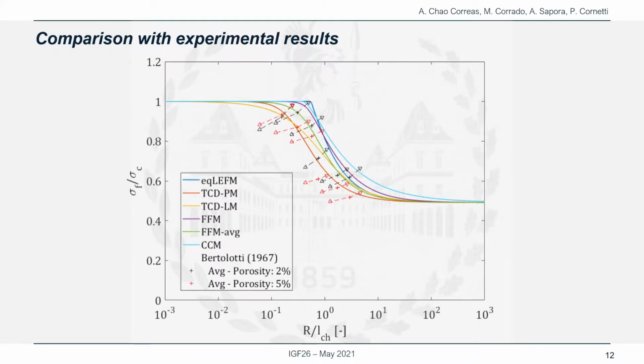Eventually, the experimental results of Bertolotti and Fulrath are a useful tool to check the validity of the method presented and developed here. However, the brittleness of the material used, borosilicate glass, makes it really important to control the experimental procedures. For this experimental campaign, Bertolotti and Fulrath introduced controlled porosity in borosilicate glass by adding nickel spheres during sintering. After cooling down, the particles, which were surface treated so as not to adhere to the surrounding material, shrank more than the ceramic, leaving, from a practical point of view, spherical voids.